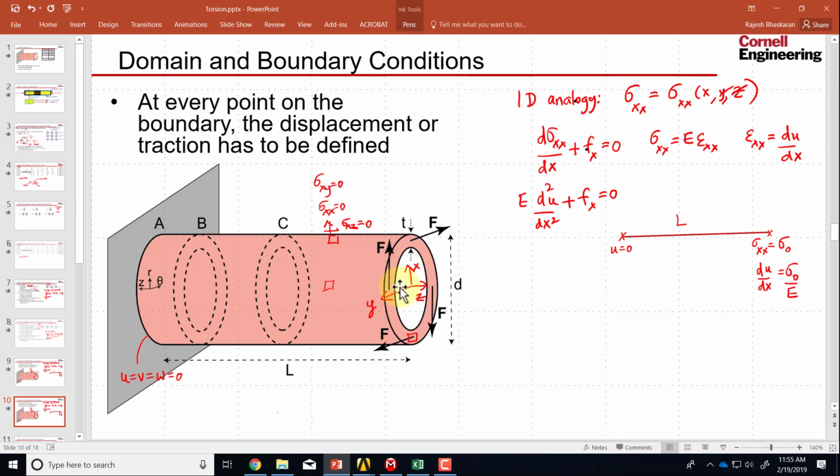If I go back here, I can specify 4 points on the surface, and I would have to go back to SpaceClaim for that and put forces at those 4 points to get that equivalent moment. Instead, what I'm going to do is use a condition in ANSYS where you can apply a moment, and essentially it will distribute forces along that face to get that moment.